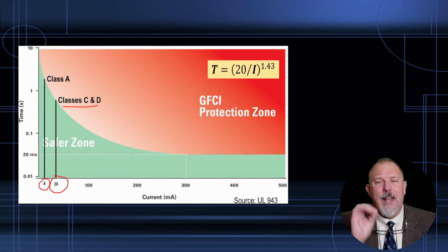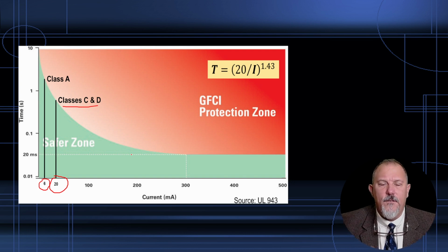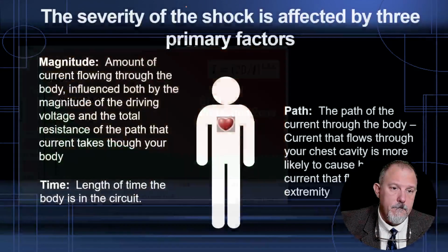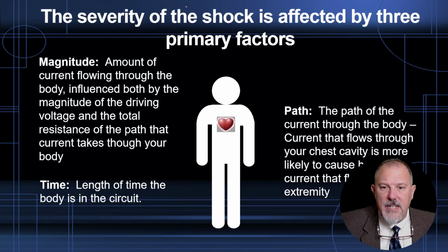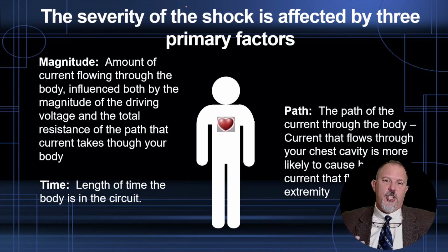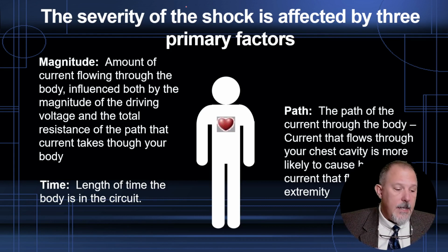Anywhere in the National Electrical Code where we say ground fault circuit interrupter, if you use those terms without anything before it, like special purpose ground fault circuit interrupter, if it's a GFCI, it is a Class A device, 4 to 6 milliamps. Now, you understand the basic fundamental principle of a GFCI is current: what goes outside of the normal path, it has to stop the flow of current.